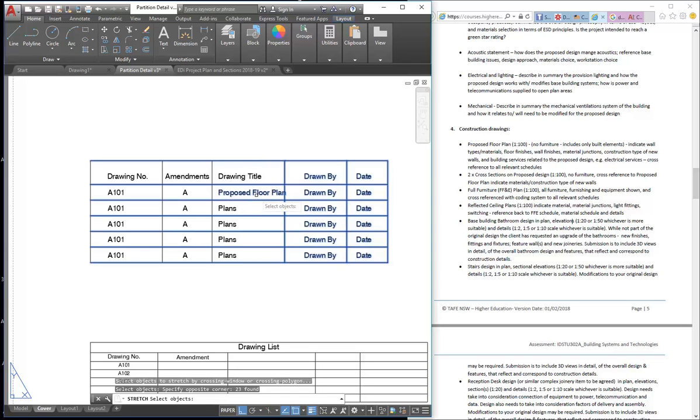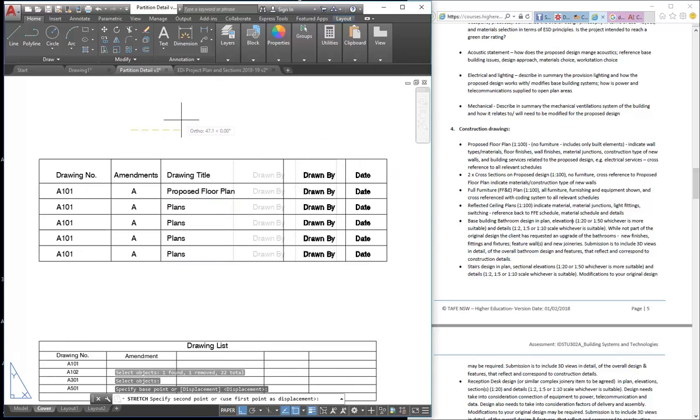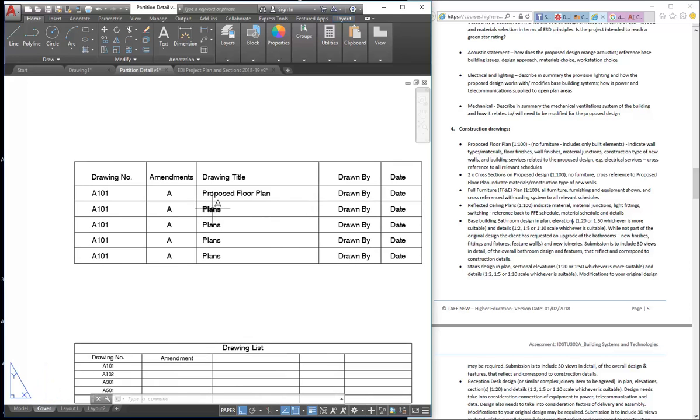It's picked up that text as well, which would actually be okay because the base point isn't inside the window, but if you want to make sure that the text doesn't move, you can always use Shift with stretch to deselect things. Now press enter and then click and easily stretch those lines across. Yeah, it is brilliant. I know things with proportions are out. So then I can just keep putting in a few other names.